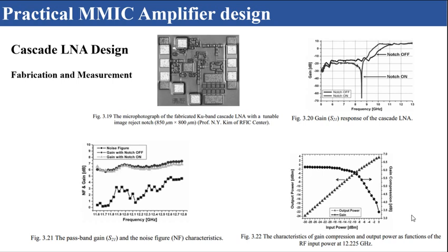Figure 3.20 shows the 20 dB image suppression region below 9.25 GHz, and Figure 3.21 shows the passband gain and noise figure response.